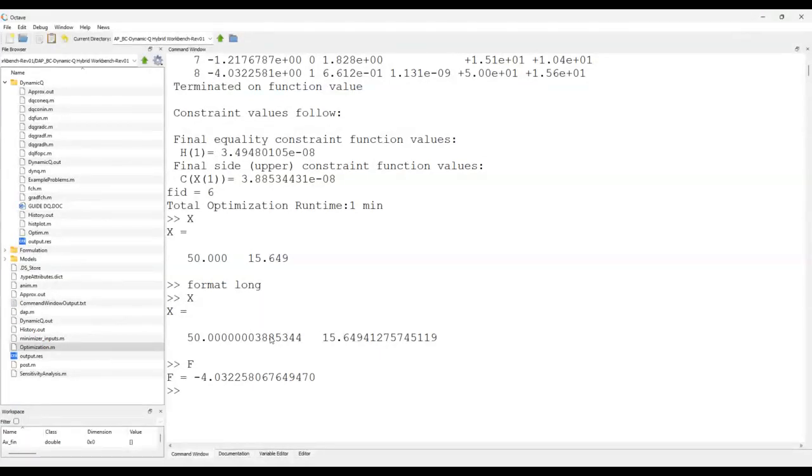Yes. So dynamic queue is a single objective optimizer. If you're interested in multi-objective optimization studies, so let's say you want to maximize your acceleration, but you also want to maximize your speed, then you'll look at those multi-objective optimization techniques. One of them is something like a Pareto optimization that you can do. Global optimization techniques also make use of multi-objective optimizations, and there are a few gradient-based optimizers that also include multi-objective optimizations.